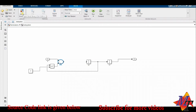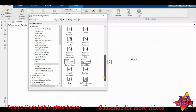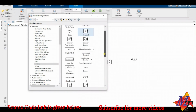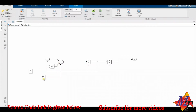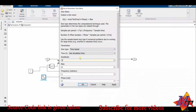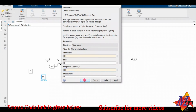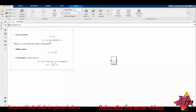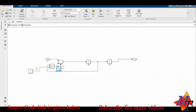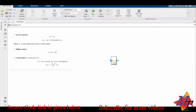So here it is x2 cube plus 0.1 sine 20t. So for that we'll take our source block, a sine wave, and we'll apply amplitude as 0.1 and frequency as 20 pi, and we'll supply this. So we have got our system, which is x1 dot equals x2, x2 dot is x2 cube plus 0.1 sine 20t plus u. Now we'll start modeling. This is our system, or we can say it is the plant.